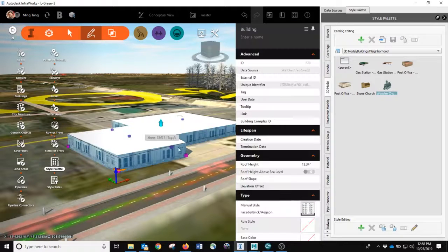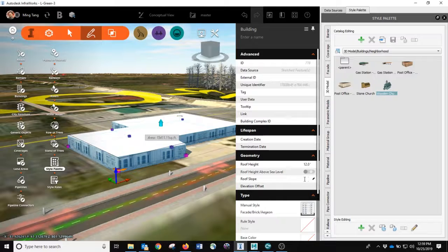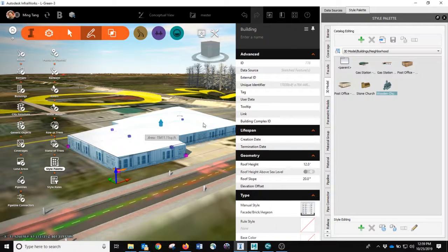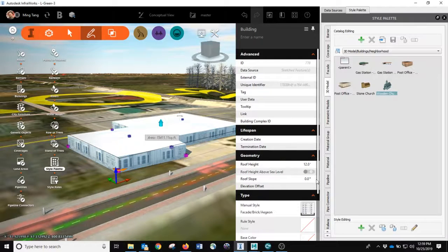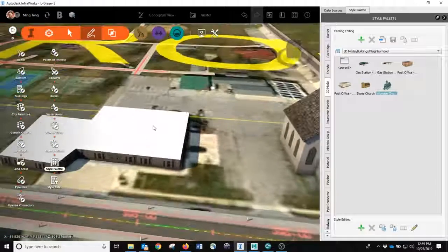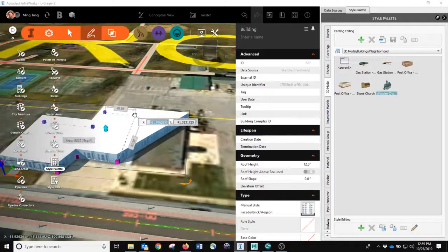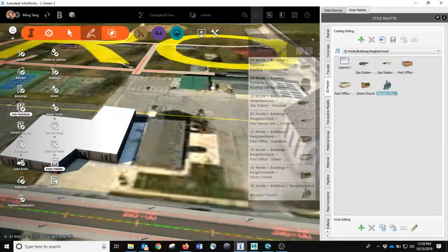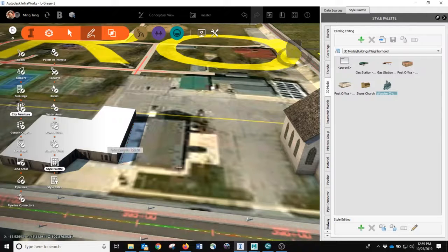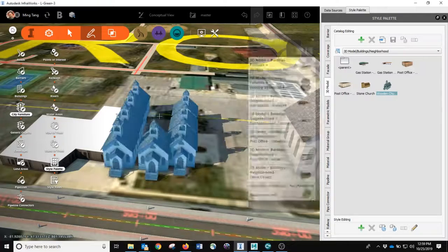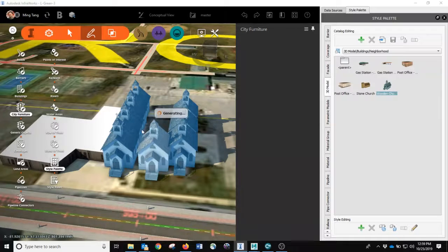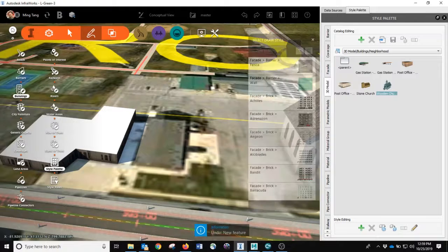And I think you can also see the roof. Let's just change this to 12 feet, and I will give the roof slope to 20. Well, actually, I should keep this as a flat, so 0. Yeah. If you do want to do another sloped roof, I prefer you just drag the footprint here, then you'll do another one just adjacent to it. So most likely this will be 2 independent. I think I'm using the wrong one, not city furniture, the building.